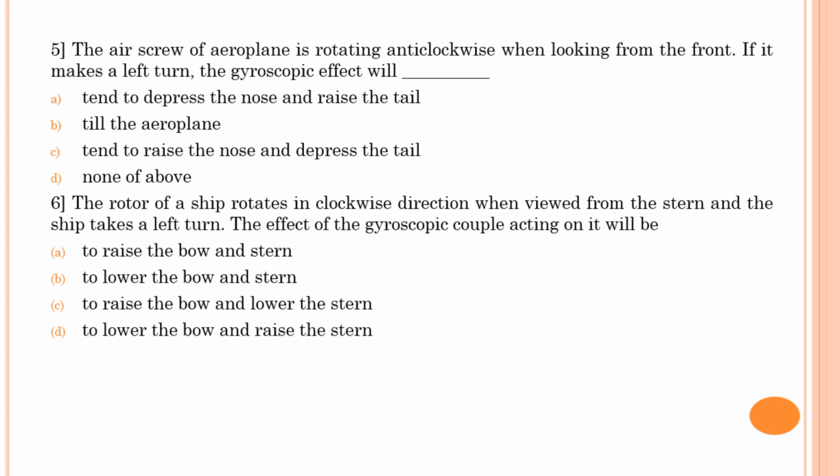That means it is the same question, from the rear end clockwise or from the front anti-clockwise. It is making a left turn, so the gyroscopic effect will be the same, but they have asked it in a different manner. Therefore the correct option will be to raise the nose and dip the tail, or depress the tail. Option C will be correct for this question.